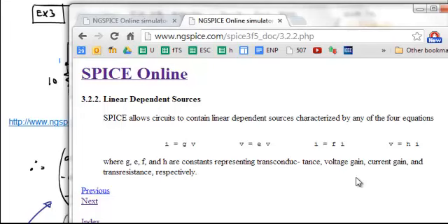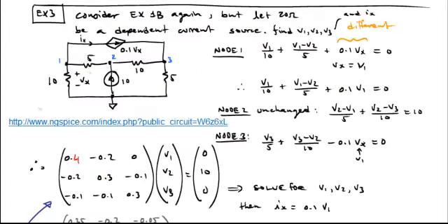So there are current and voltage outputs, and the controlling signal for each of those could be voltage or current, meaning you get 4 permutations. So in our case here, we have what's called a voltage controlled current source. Why? Because the output is a current source. It produces current, but it's controlled by a voltage Vx. So it's a voltage controlled current source.